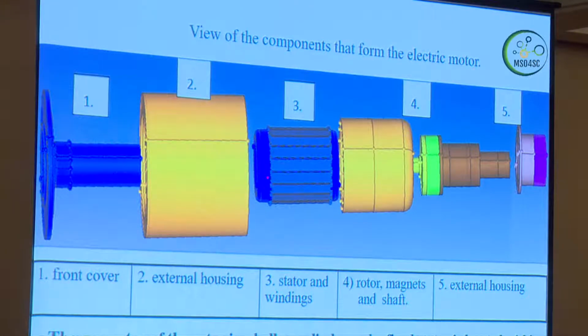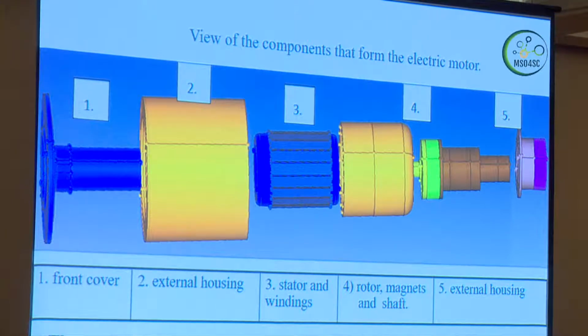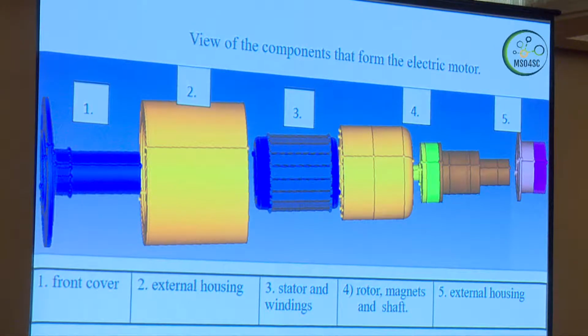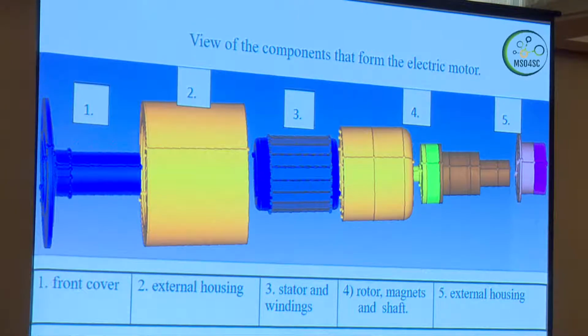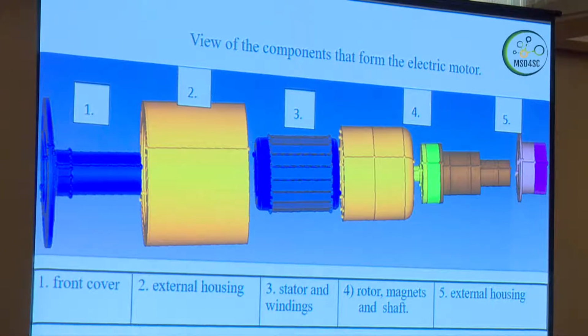It's here, it's the winding. This is the copper. And the winding region is modeled as a solid region because here we have three materials: the copper, the insulation material, and the area between the electrical parts. And the head of our winding is modeled as a torus.